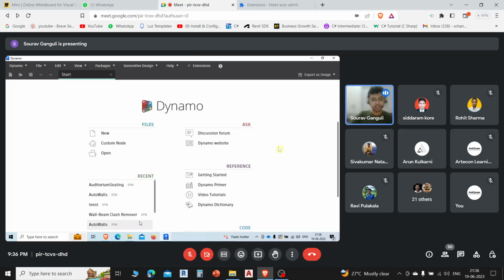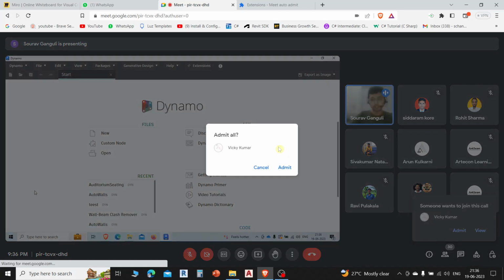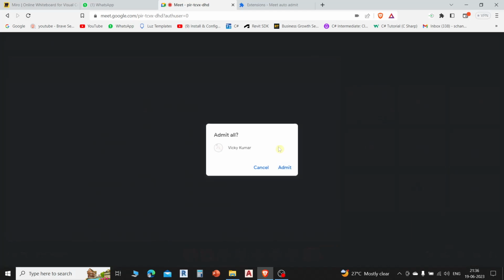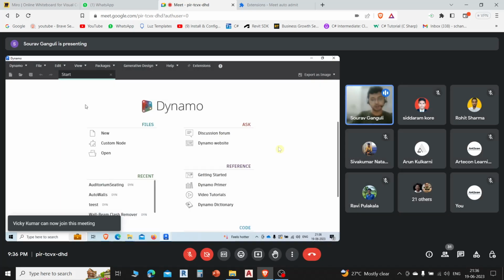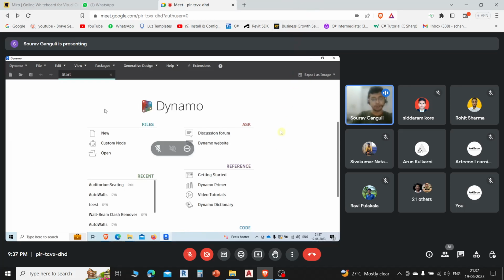Then there's a recent portion, which is just recent files of all the recent scripts that I have been working on, along with a few quick links to the Dynamo discussion forum and the Dynamo official website, along with a few learning references. If you are starting Dynamo for the first time, you may have some terms and conditions to agree to when you run it. But once you do, this is the first screen that you should see. The screen may vary slightly depending upon the Revit version you have, but most of the things should be the same. So to start Dynamo, the first task is to click on New.